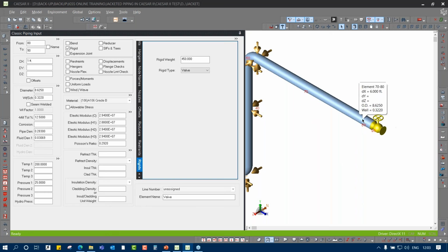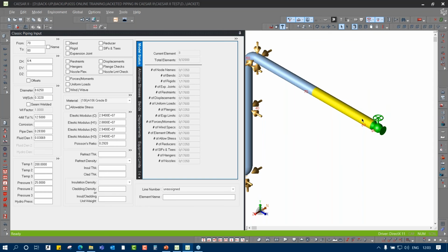Whenever I get these kinds of things, as per the valve, there is no jacket piping on the valve, so I need to terminate my jacket piping. The way of terminating my jacket piping, I need to weld my jacket piping onto this area, which should be coming in my jacket portion, not in this portion. So let me go further. Again, 6 feet.